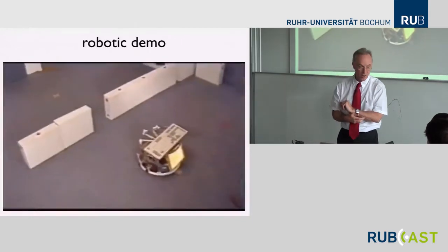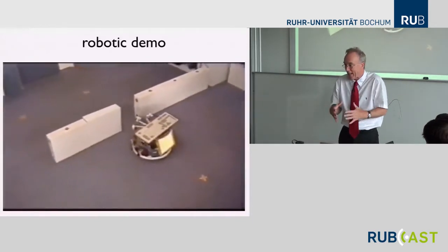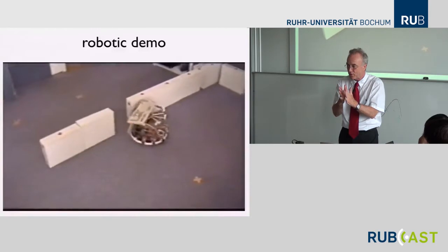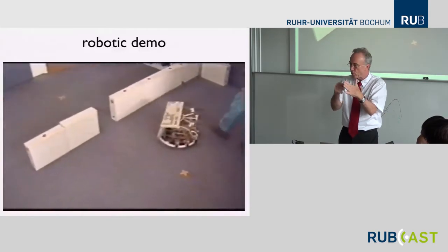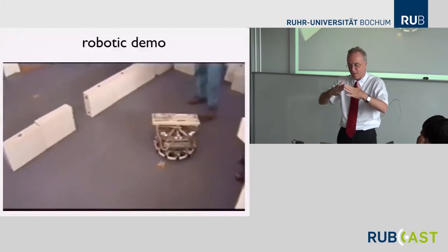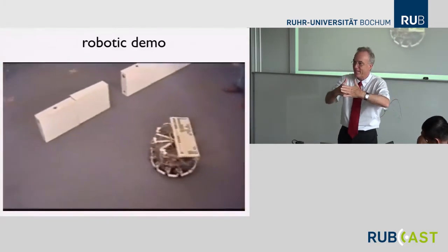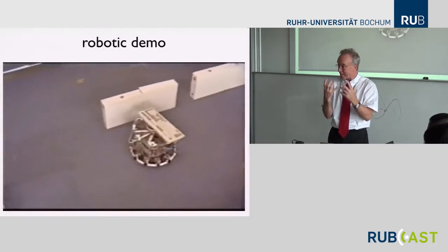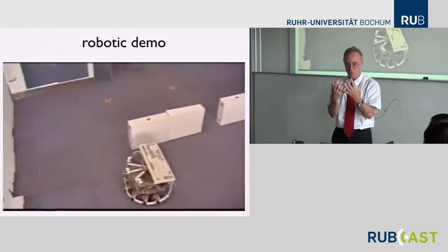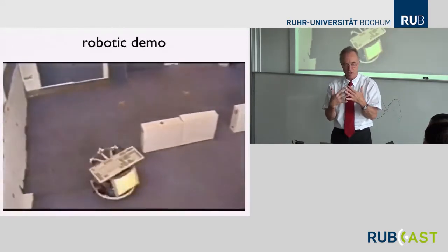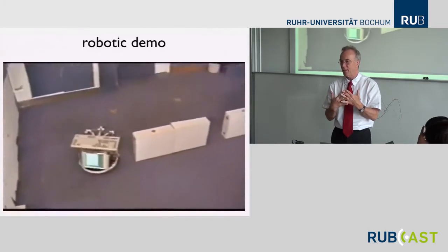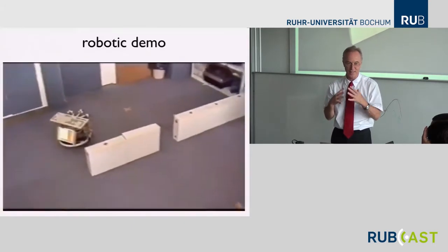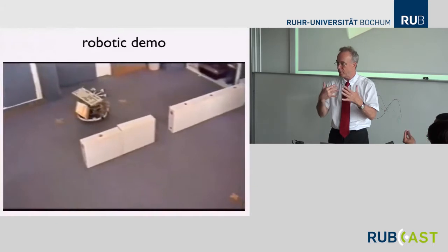And of course that's totally non-generic, because you would never get into a circle like that if you had that approach. And if the circle is a little bit narrower, then you're going to collide on one side first, and our approach works. If it's a little bit more open, then one sensor gets closer, and the whole thing works. So the approach is not exact. There are cases where it doesn't work, but those cases are hard to reach in the real world. We have no general proof, so maybe one can construct a whole ensemble of cases like that. But in practice, it works very well with this local analysis.